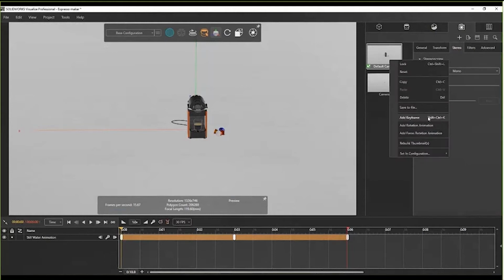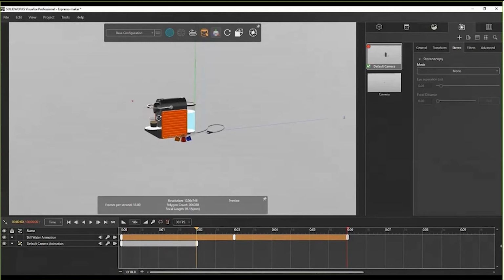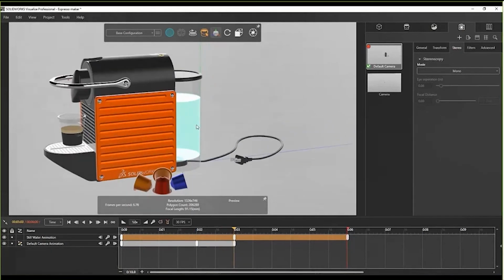So I'll right-click on the camera and say Add a Keyframe. It's going to put it at the beginning point, and over the course of 2.5 seconds, or apparently 1.5 seconds or 2, I want to do this 90-degree swivel. And then over this next second, I'm going to zoom in to this point so I can get a better look at my part, okay?